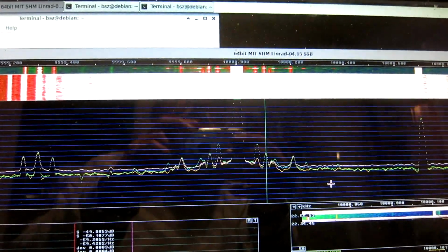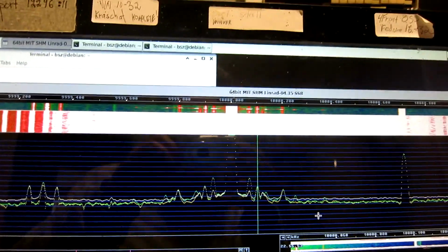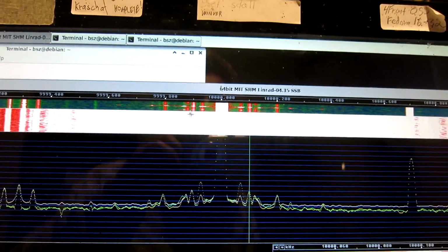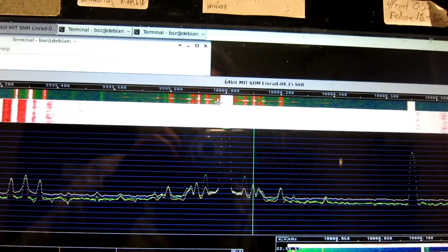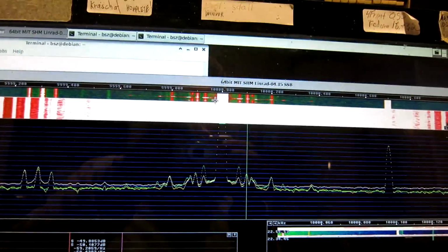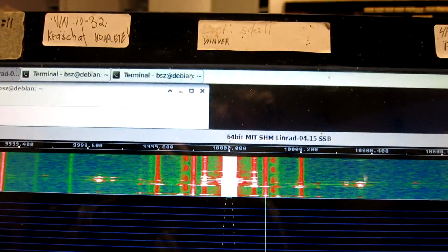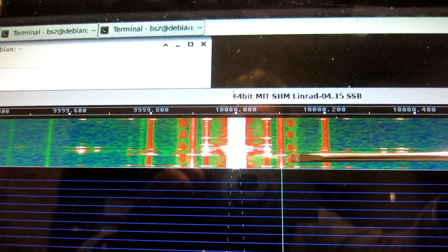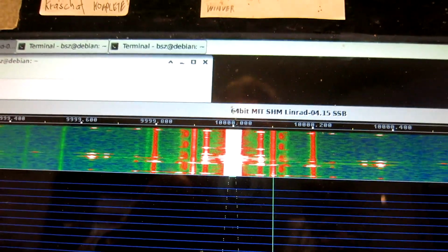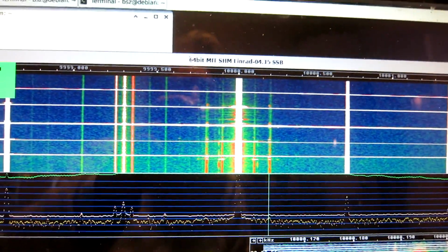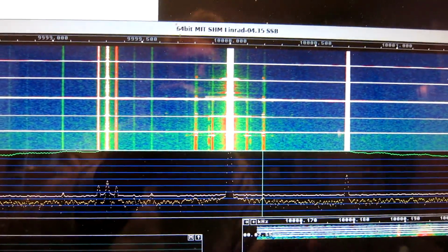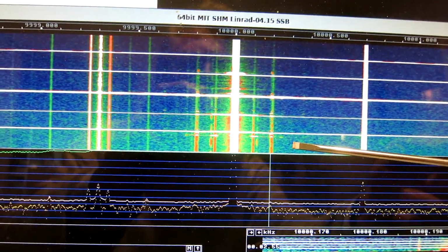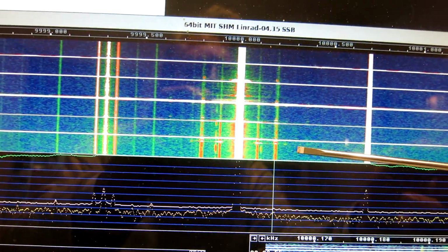And what I see now is pretty ugly. The crystal has all sorts of oscillations on the sides of the main signal because the power is too high. There are interesting patterns. This spur that comes from the crystal goes up and down in a funny way. Here I have run at different power levels. So this is with a 3 dB setting on the attenuator, the maximum power that the crystal should accept.